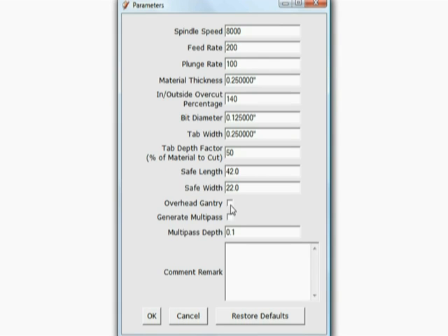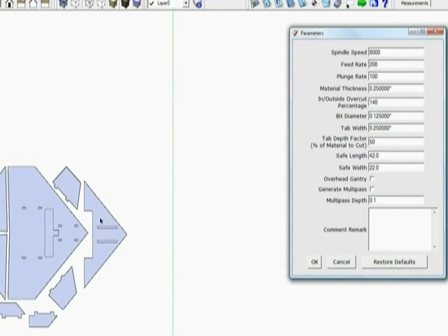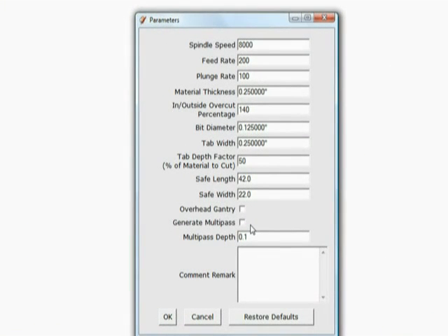But then also, how deep do I make each pass? Do I plunge completely through the material and cut it all in one pass? No, not with harder materials like that. Generally, I try to make cuts of about 1/16 of an inch. So if this were MDF that I were cutting this plane out of, which is kind of silly, then I might say, well, I know my machine can use a 1/8 inch bit and can easily do 1/16 inch passes.